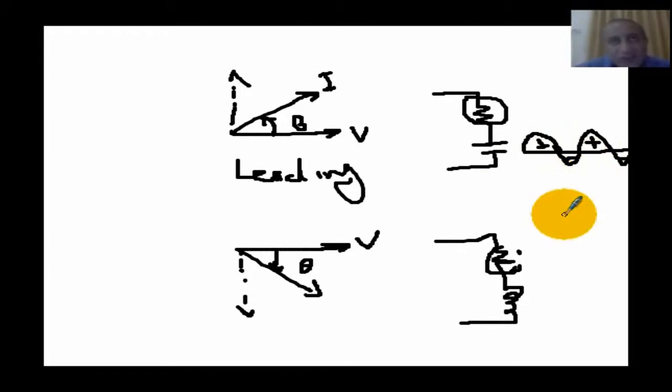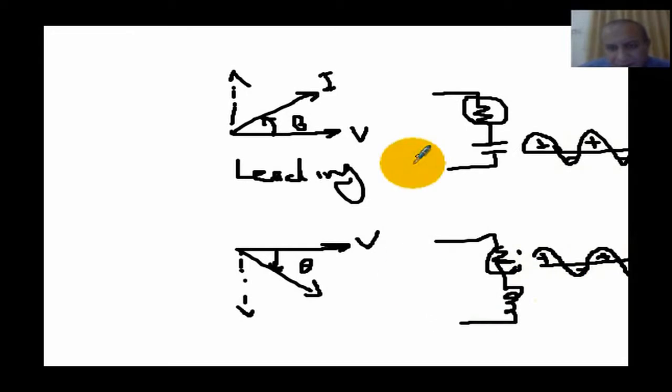So this is a load on generators, a load on transmission lines, to have some current going back and forth, not doing any useful job. Similarly, in the case of a pure inductor, 90-degree angle, as I demonstrated a few minutes ago, we have positive, negative, positive, negative.